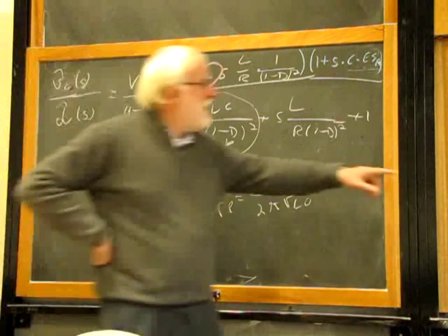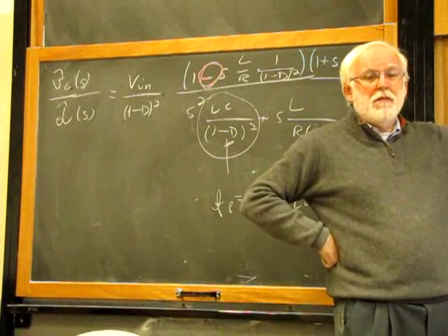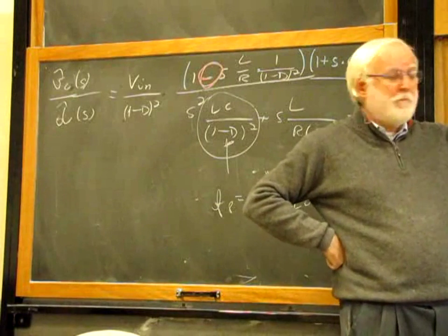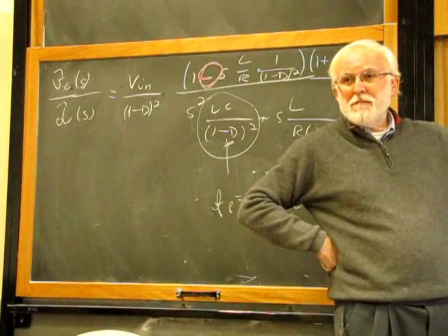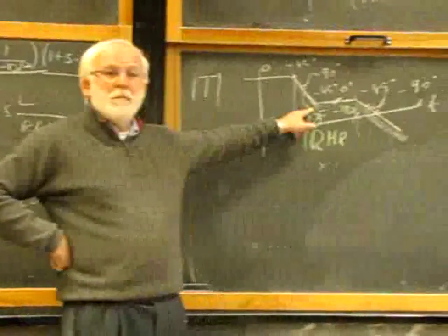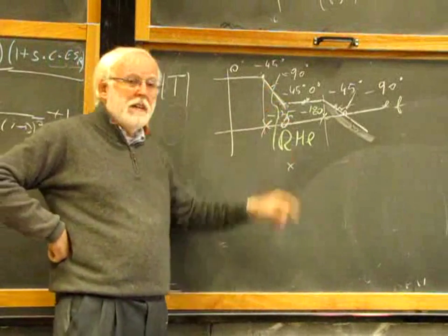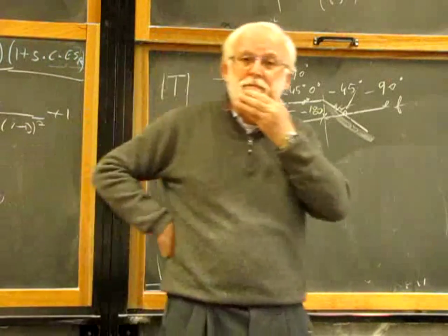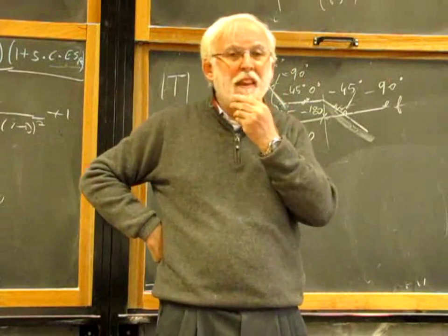This zero is higher than 10 Hz, and so I can use a boost converter in CCM for a PFC because I have to cross over at 10 Hz. But in any other case, be careful because you have to cross over far below this right half-plane zero frequency. Okay? So far so good?